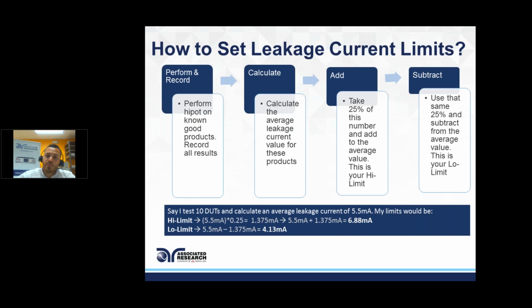That way I'm not breaking down, but if I have some insulation that's leaking a lot more than I expect of my product, you will at least be notified of it. Does it mean you failed? Yes, it'll say high limit failure, but as far as the standard's concerned, you didn't fail. No breakdown occurred. But for your internal quality, you now have noticed that this product is a lot different than the rest of my products. Let me investigate.